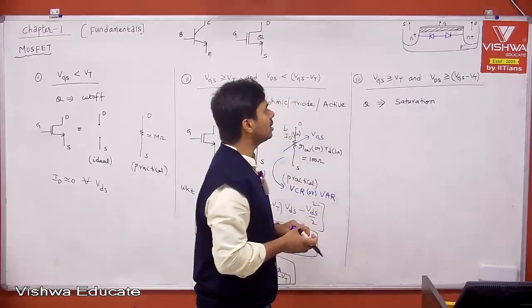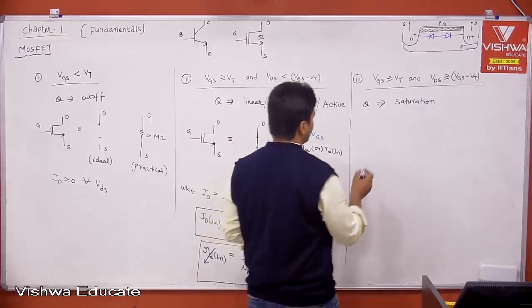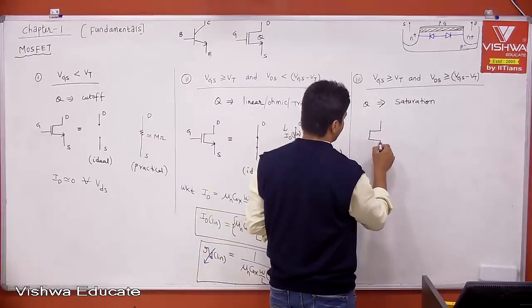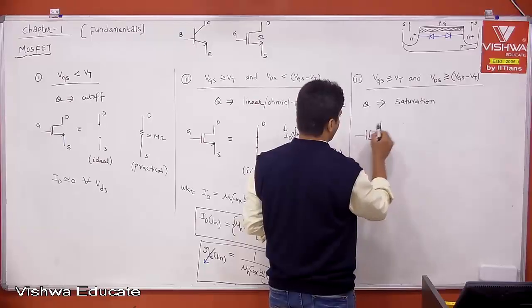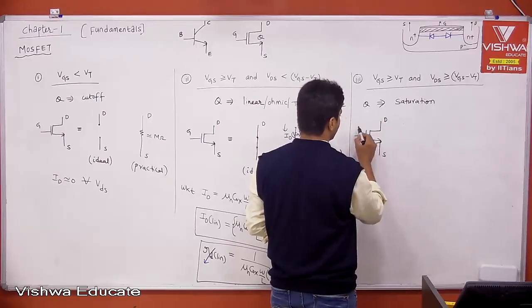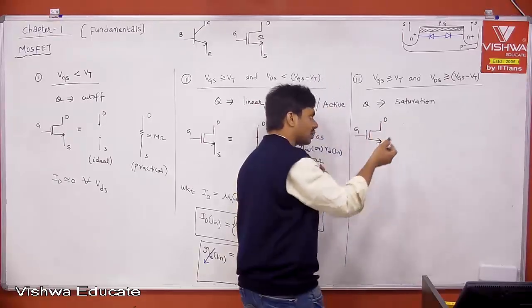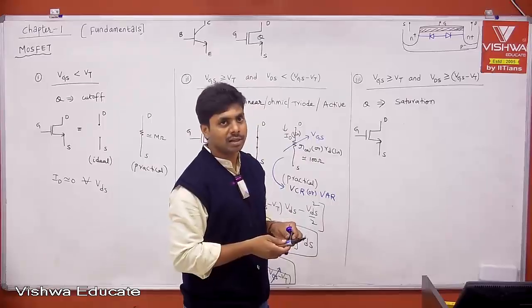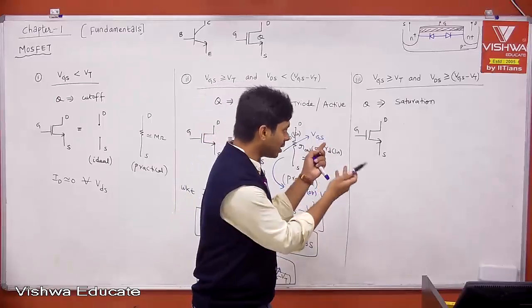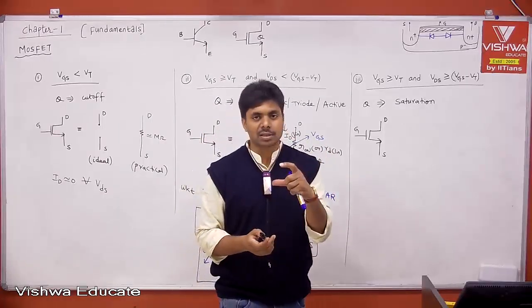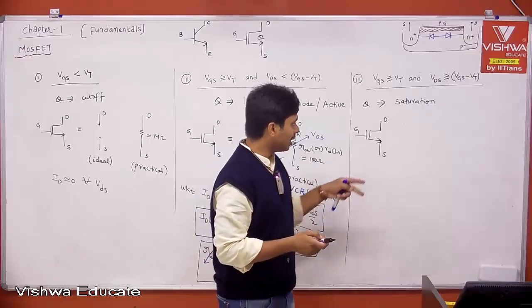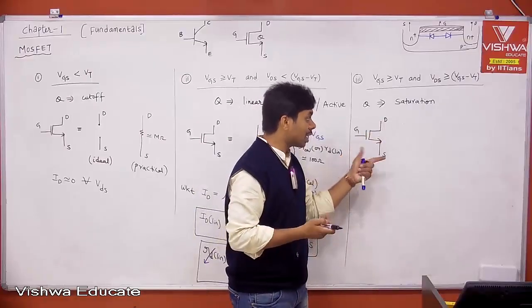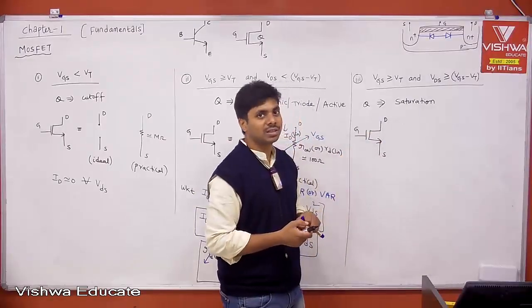Now, when transistor is in saturation, then what is the representation? Then when I say this is your MOSFET, drain, source, gate. See, the voltages are defining the state of the transistor, right? Therefore, when you change the voltage, the state of the transistor is different. Same transistor having 3 terminals, right? The state between drain and source is controlled by your gate to source voltage.